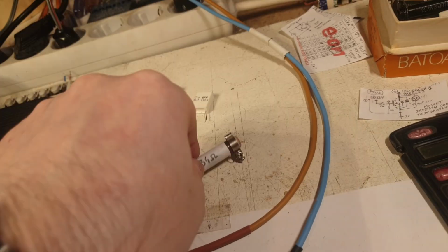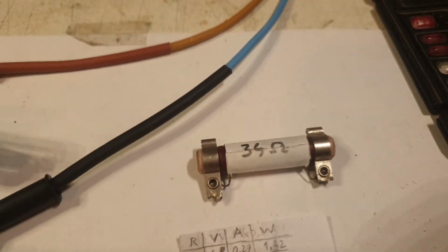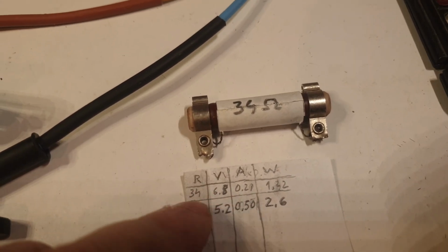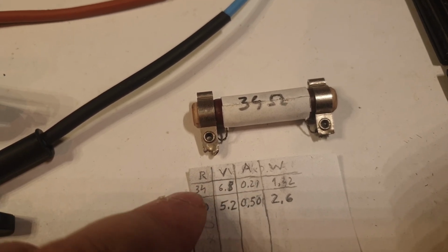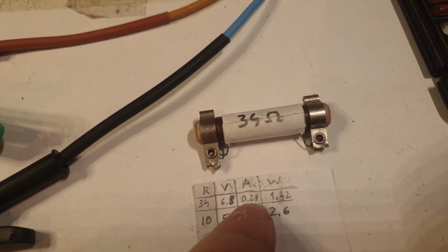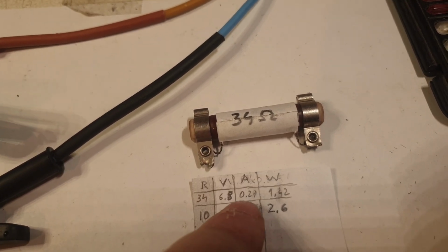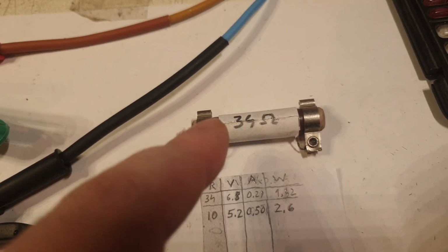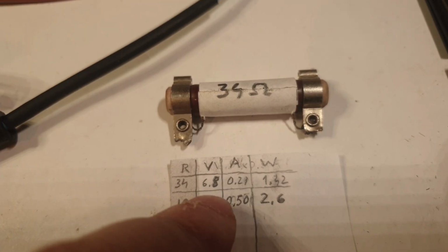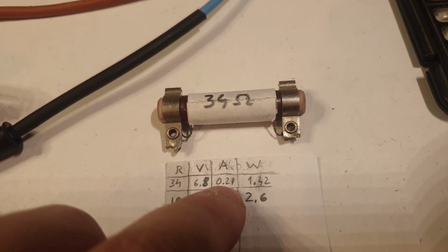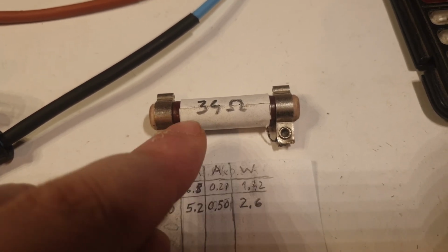So I tested this resistor originally, this 34 ohm resistor here. And the voltage, I intentionally doubled it to 6.8 volts, so 34 times 2 is 68. So here, 6.8 volts. It gave me 0.21, and I was expecting 0.2 amps, and I totally get it. So this is another way to test the true value of a resistor with voltage and amperage. Originally I tested it at 3.4 volts, and I got 0.1 amps. So this is how you tell the exact value of your resistor.